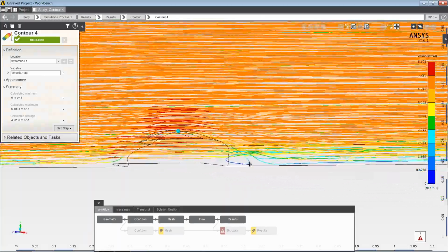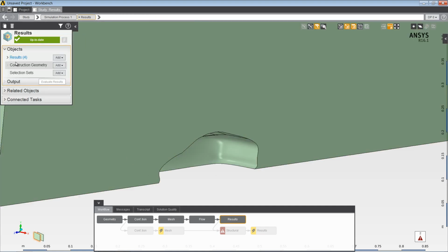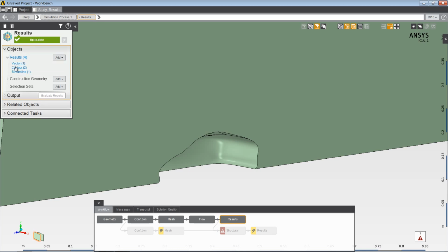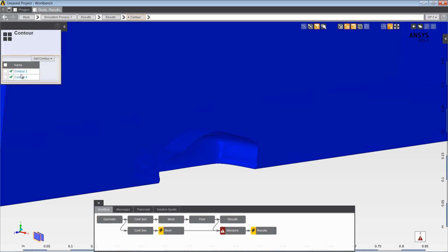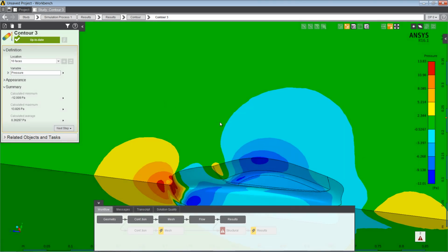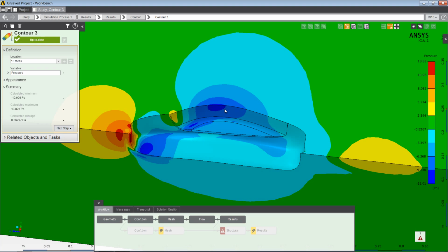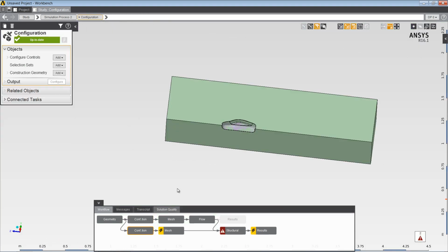Following the flow simulation, the structural deformations need to be calculated on the basis of the pressure distribution. This pressure distribution is uneven. So here we have another image. Different pressures arise in different places, and this pressure distribution should be transferred to the structural model for the purpose of calculating structural deformation, in order to obtain the correct and precise load.